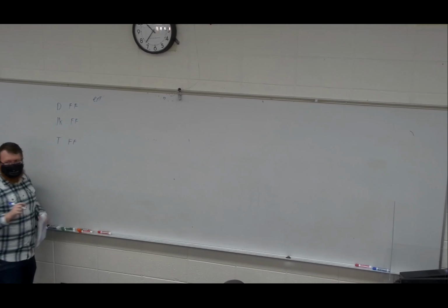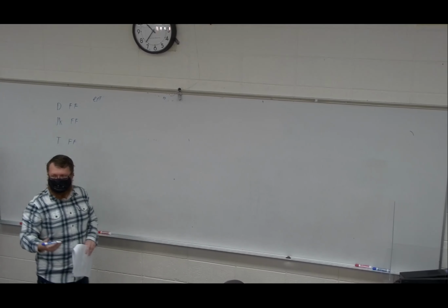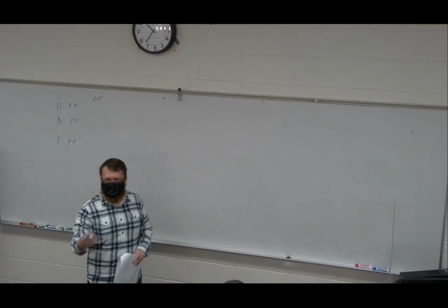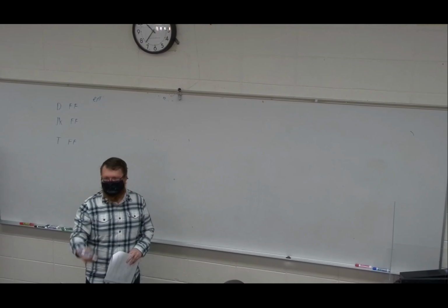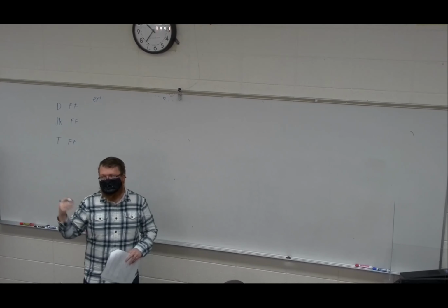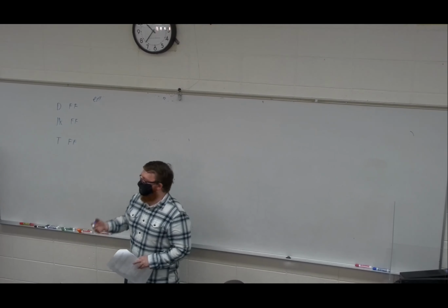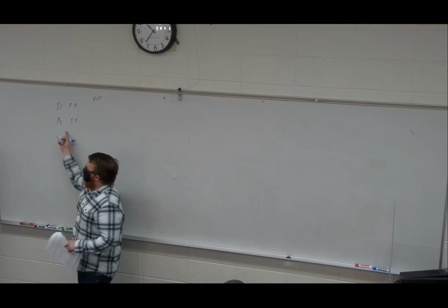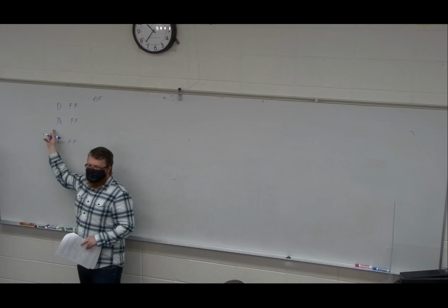Now, the D is pretty simple, in that on a rising edge of a clock, it just takes whatever is on the data line D and puts it to Q after some short delay. The JK flip-flop does not have a data line.